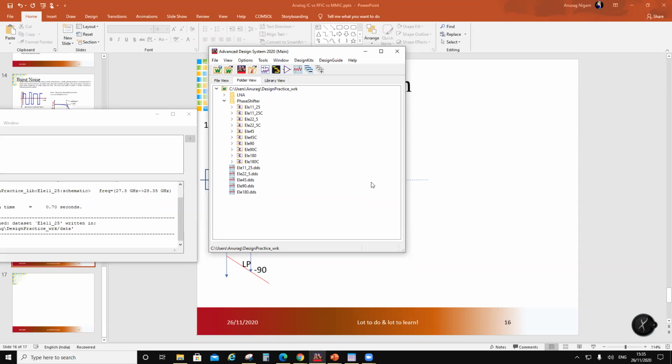My opinion is, once you have gone down in angle to such a small angle, you need not implement this as a high pass, low pass. You can just take two lines which differ in phase by 5.625, and that's it. That will be your LSB. Now you are going to tolerate some mismatch on these phases, or what you call the RMS error. If that error is less than half the LSB, that will be tolerable, right? So you should be able to do another bit using two transmission lines differing in phase by 5.625, and you will be done with it.